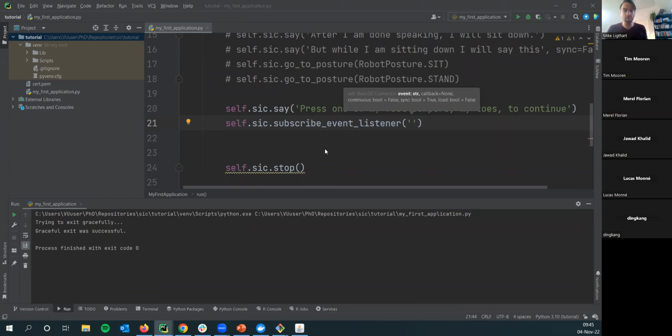In the active mode, the motors are on. It needs this, for example, for standing up, the motors need to be on, otherwise it will slump over. You can't move the arms when it's in passive mode, and it needs to be in active mode in order to move. So if you say go to posture, but it's still in passive mode, then it wouldn't do this action. So it needs to be in active mode to be able to move.